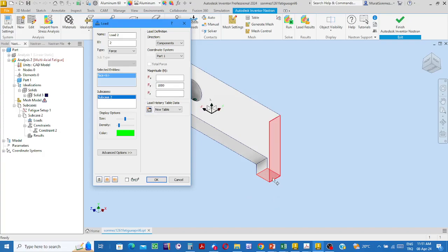But in this example, since the tip of the valve pushes this end of the object, thanks to the existence of a restoring spring in the mechanism, the stem of the valve cannot apply tension force, it can always apply only pushing force, compression force. But the force will change from 0 newtons to a maximum of 1,000 newtons, and then gradually decrease from 1,000 newtons to 0 newtons.